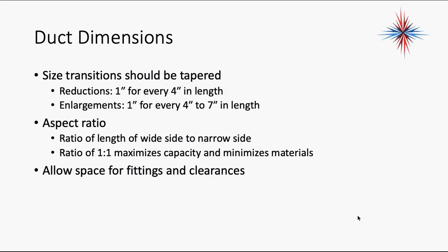New construction, one of the biggest problems that I've seen in new construction is they put the air handlers and ductwork in the attics before they put the ceilings in. Okay, so your company goes out and places the air handler, puts the ductwork in, and then the sheetrock contractor comes back and puts the ceilings in. Okay, then they put the attic access in, usually pull down stairs or an attic hatch. You might have your air handler in a space in that attic that doesn't have any more access. In other words, you can't fit over the ductwork to get to the air handler because you were trying to be the nice guy and put your air handler off to one side that allows them to use the attic for insulation and storage.